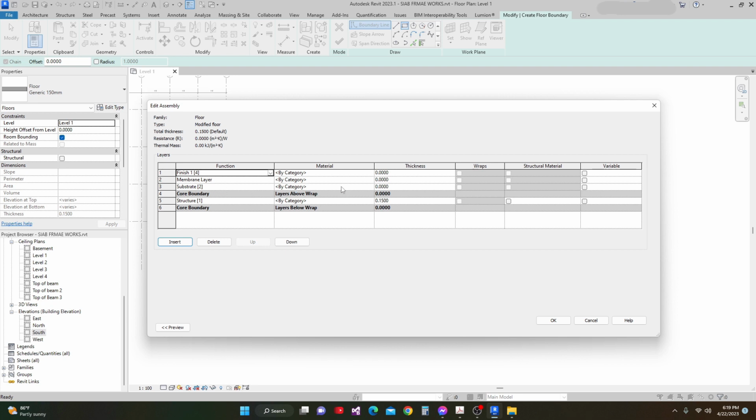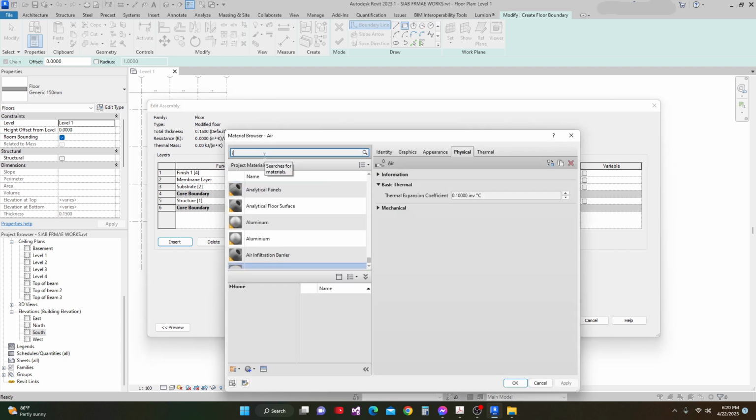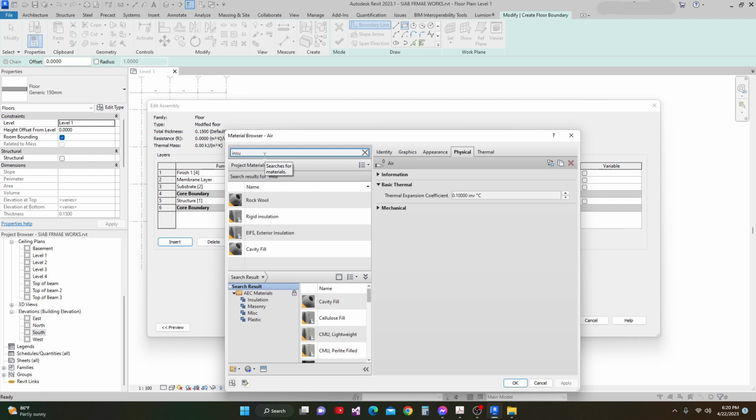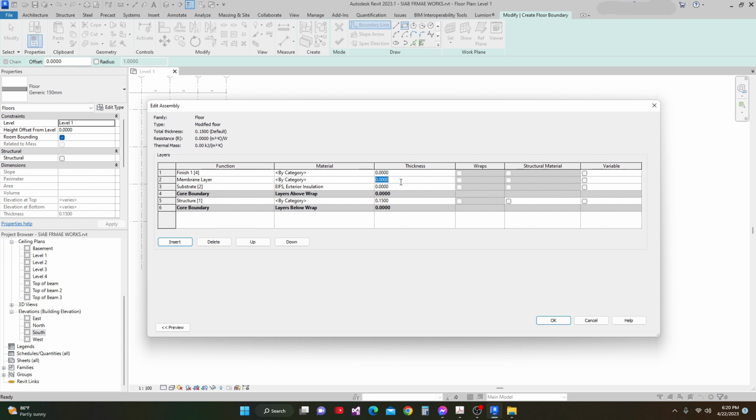So for example, our substrate is always an insulation, so we're going to find a material, insulation, then we'll adopt this, and then okay, and then make a thickness of insulation. Here in Pakistan, they always place an insulation of gravel. They are placing gravels of 6 inches, so we'll place also 6 inches. And then also membrane, we will not place anything on that membrane.